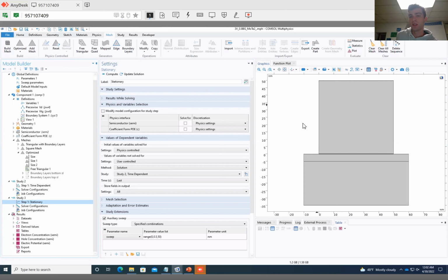So to do that, we basically have to reduce our units by 1. We can do that by integrating, right? If we take per meter cubed and integrate that, we can get per meter squared. So to do that, we have to run this extra study, to do that within COMSOL instead of exporting to something like MATLAB, which has its own issues we found.